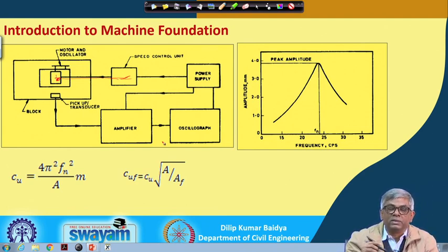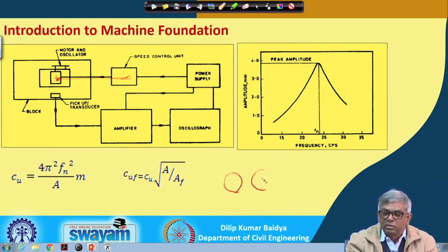Once you change the frequency, in this vibrator, this oscillator, there is a rotating mass type of system. There are 2 counter rotating masses, as I have shown before also. If one goes here and the other comes this way, they will face each other and get cancelled. When it comes in this direction, and again in this direction, it will be cancelled. So, it only produces this vertical vibration.